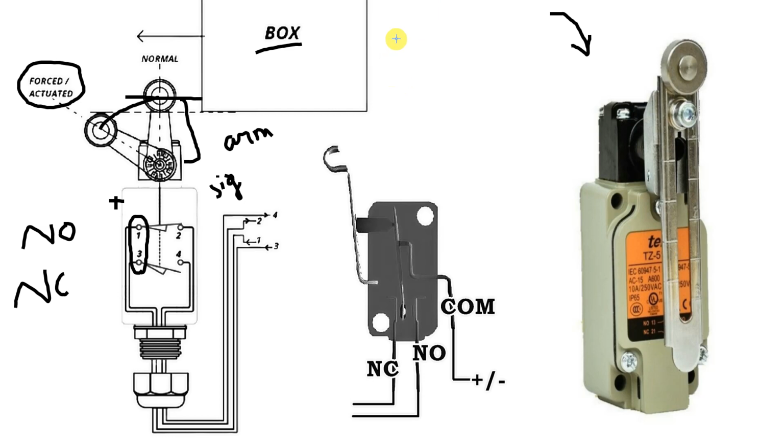When you are using the limit switch as a safety device, and you want to stop a critical operation, go ahead and use the NC terminal. If you are using the limit switch for triggering something, for giving pulses, for counting, or for checking presence, then it is advisable to use the NO contact. Why is this? We are going to cover this when we discuss industrial logic and PLC programming.